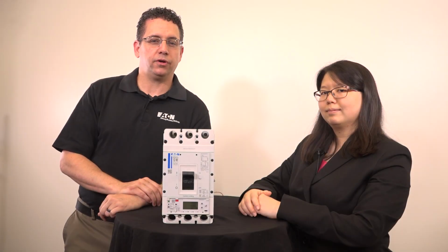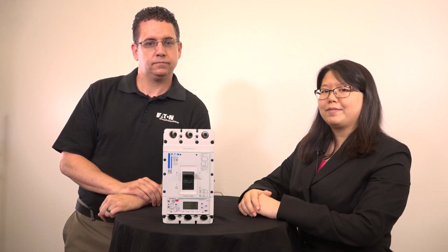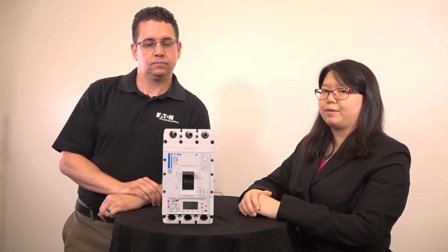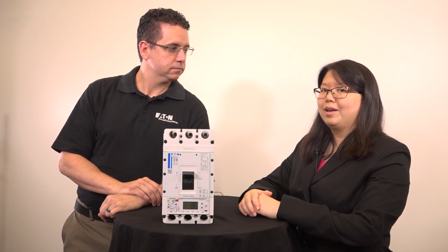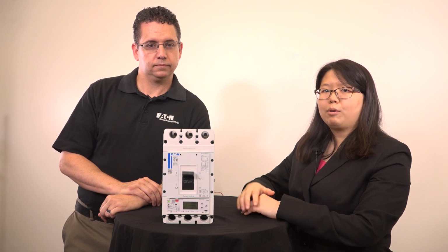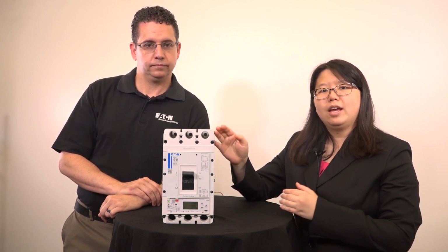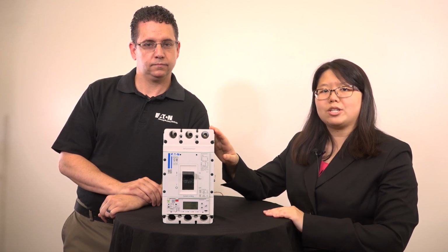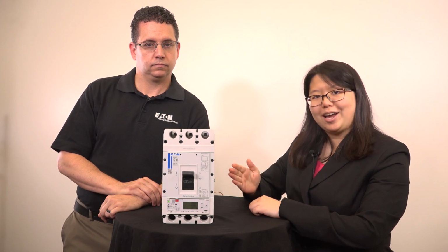What do I actually do with all these Setpoint files? Let's say you've only got a limited amount of time to access the breakers you want to configure. You could do all the configuration work without a breaker before you even set foot on site. Then, once you arrive, programming the breakers is easy. Unable to make it to the actual site? Create the correct offline configuration and send the file to an electrician or maintenance person at the facility. Here's how you do it.